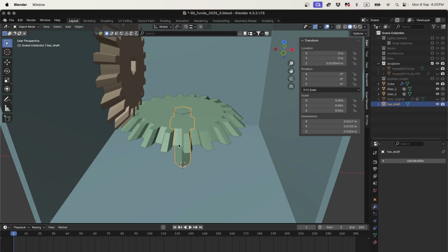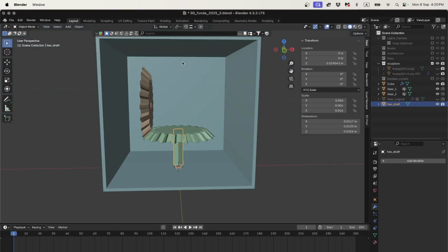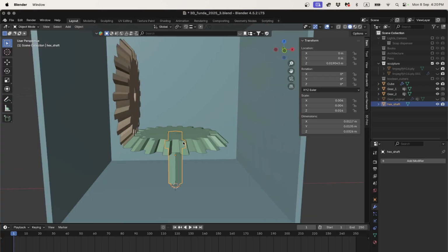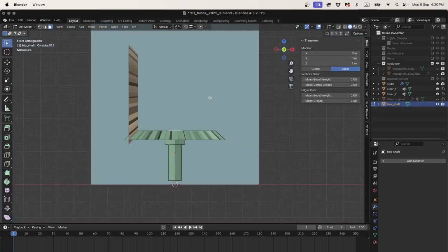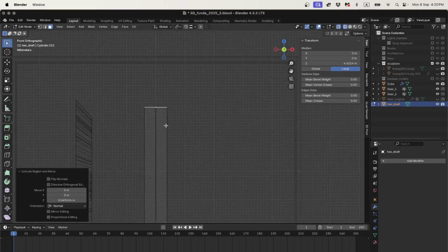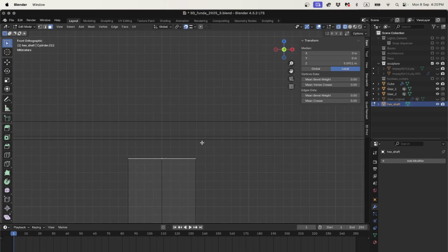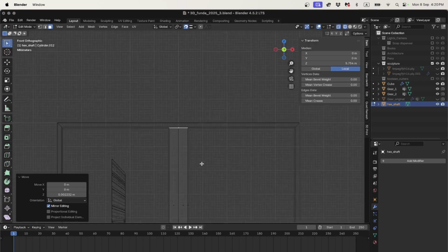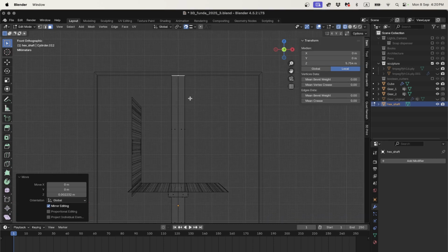The last thing that we will probably have to do here is send this rotation up this way somewhere. So if I go back into edit mode, I grab this face, we might just E, go all the way up. I need to go into my wireframe to see how high I'm going. Press GX and then turn on my snapping. Now I'm probably not going to make it exactly this height, because that might make it difficult to squeeze into the shape.